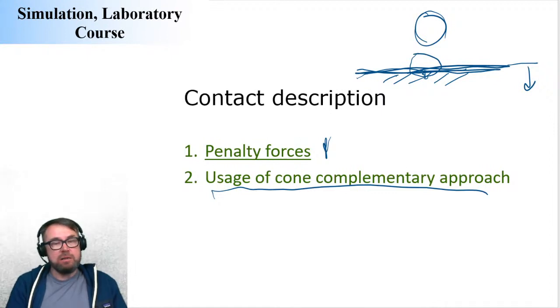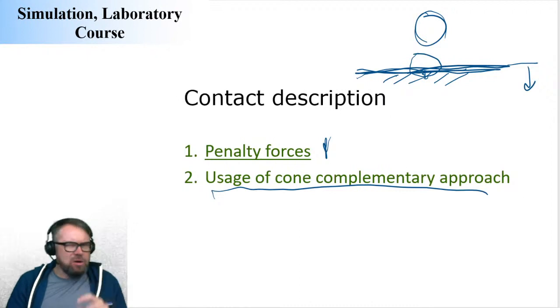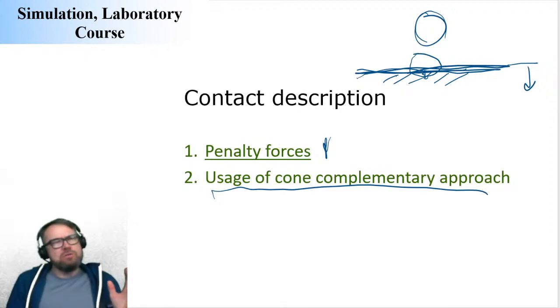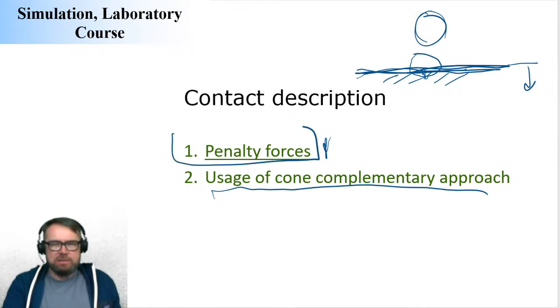If you wanted to model an off-road vehicle moving on an off-road surface, and you wanted to make the ground deformable, one way to do that is by using a lot of bodies. So it could be like sand particles, not as small as sand particles, but close to it. That could be the way to describe this deformable ground. This is where many-body dynamics comes into play. But let's get started with these penalty forces.